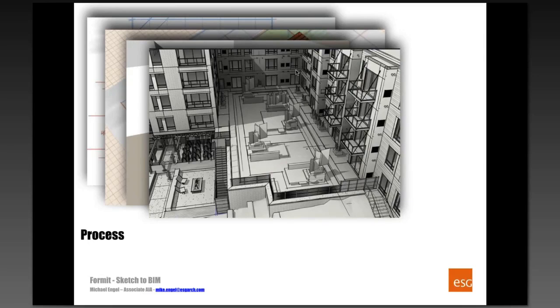And then, which is one of the magic things about FormIt, is having, in many ways, a direct connection back into our Revit model. In this case, we had a Revit model that was articulated and detailed in CDs and very robust, which from a design point of view is sometimes cumbersome. But with the ability to go back and forth between FormIt, you can see that the FormIt model is directly inserted in a real location into the background Revit model as native Revit objects.